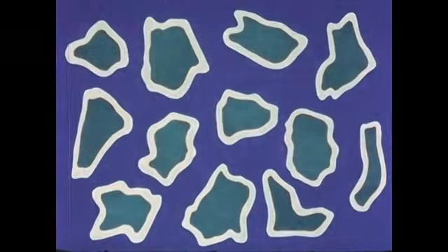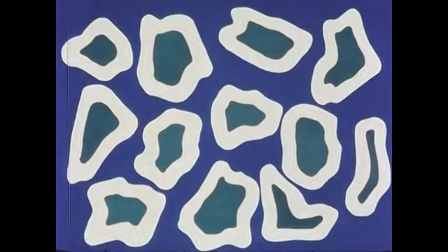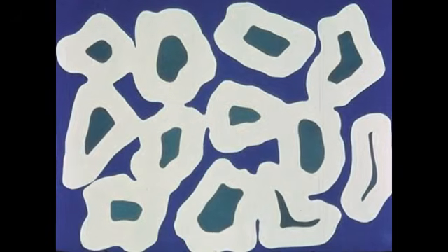If you magnify a particle of cement many thousands of times, you will see the water and cement chemically react rapidly at first, then more slowly, until virtually all the cement is combined with the water. This process is called hydration and continues as long as moisture is present and temperature is favorable. In the paste, particles of cement hydrate at the same time to form new gel-like substances that harden and strongly interlock, binding the aggregate together into a rock-like mass.